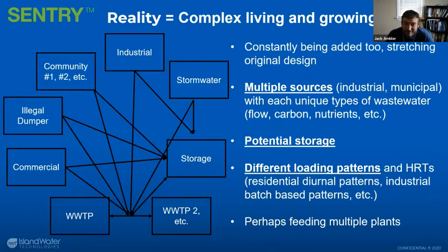All these different impacts have their own unique patterns. They might be very far out on the collection system and take a long time to get to your system. They might have a batch cycle. They might have a diurnal pattern. So all these are coming together and feeding into the wastewater treatment system.